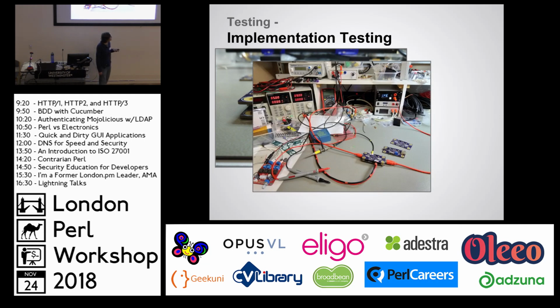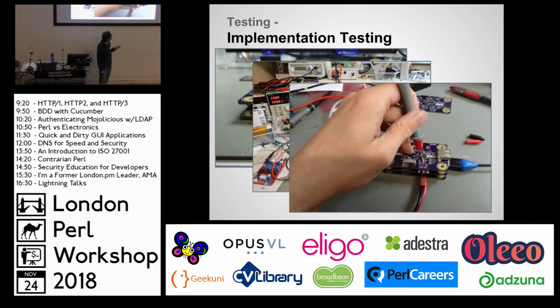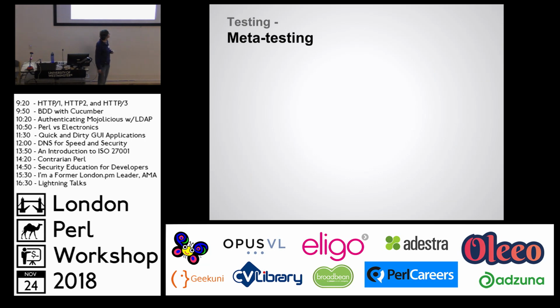So that when you want to test it, you can connect all of your little test wires and things to that bed of nails. And then you take your real board that you're actually testing and you just push it onto there, and all those pins make a connection and connect off to all your test equipment, and you can see, does the thing work? Yes, wonderful, put the next board in. And it takes you like 3-4 seconds per board. So much nicer than using all those little test clips. If you're doing these things in volume, if you're making lots of them, you need that quickly. So there's a nice little testing thing.